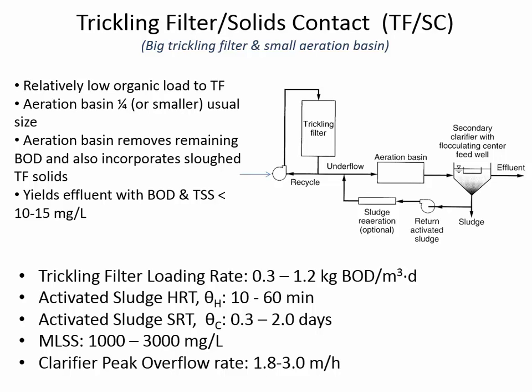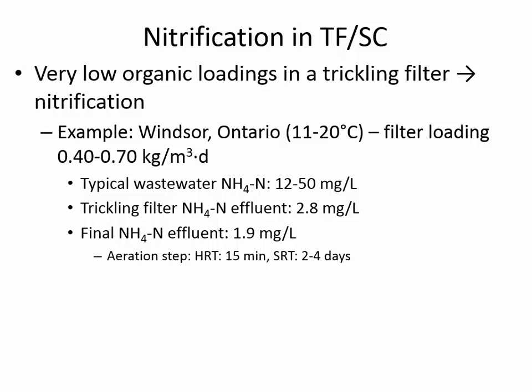And you know, in a more typical activated sludge, it could be half a day, maybe a day of hydraulic retention time. And so it's a very short contact time in the aeration basin. And the solids contact time is also pretty low. In typical activated sludge, maybe the median value would be 5 days for the solids retention time, but in the solids contact, it could be as low as 0.3 days. And so the aeration basin is the afterthought in trickling filter solids contact.